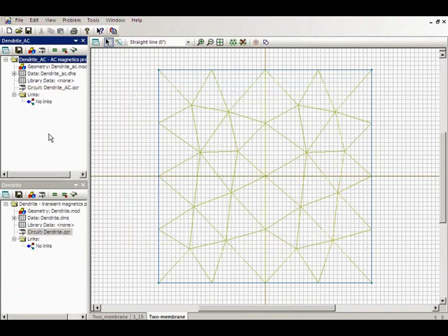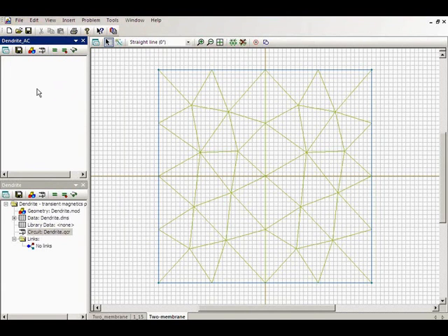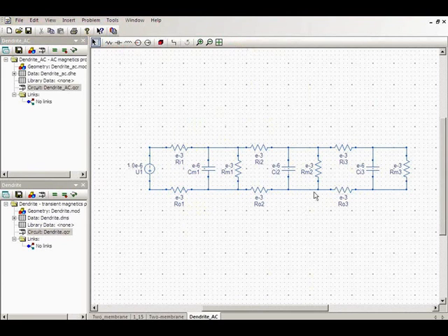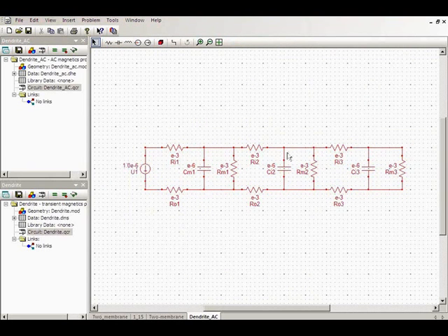And we'll look at the AC excitation of a dendrite. So we're applying an AC stimulation. Now, once again, there's a model file that is not associated with the circuit at this point. So we're just running the circuit simulator without an attached finite element block. And this is our dendrite model. Now, we could continue to add elements here. This is roughly 3 elements.